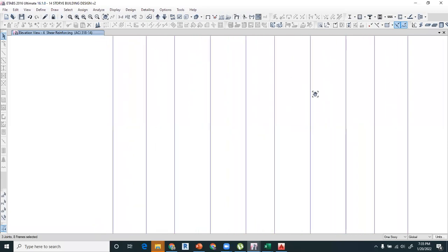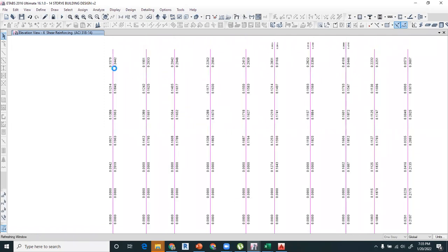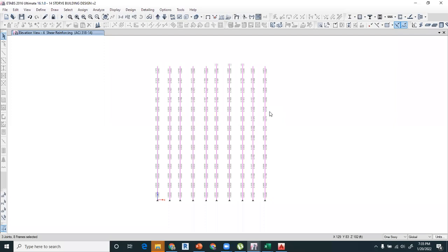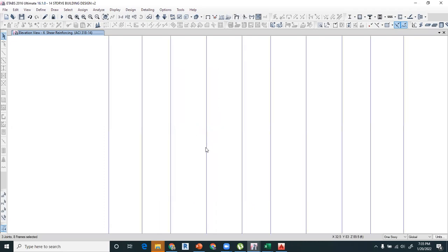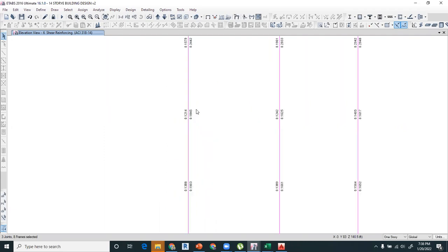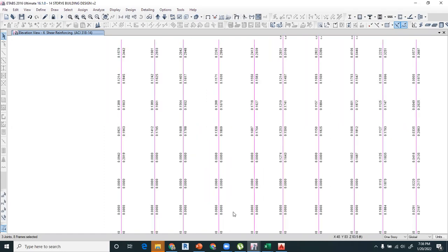So if there is no reinforcement asked, when you calculate this, you have to apply it again for all the columns. If you are a very good engineer and you have a very good draftsman, he is able to provide different sections with different detailing. So you have to provide up to some story where there is no demand of the shear. So you have to provide the minimum reinforcement of the shear, and then after that, on those stories in which the shear demand is high, you have to go for those spacings which you have calculated in your design.